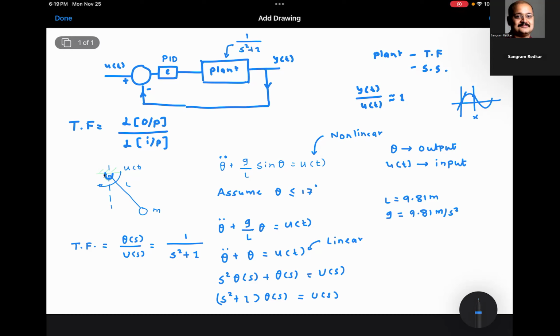And we would use PID controls, or we will design the PID controls that are valid in that region. As soon as the aircraft transitions from the first region to the second region, we would change our gains. Everyone understood this?